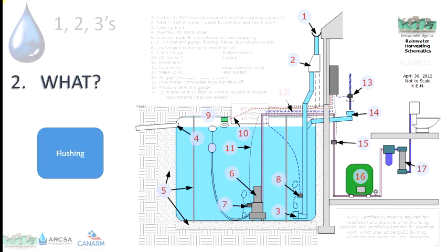And there's a floating intake which allows the water from about 6 inches below the surface, wherever that surface is, to be pulled into the pump. That is the sweet spot for good water in the tank. Not the very top, there's floaters always, and always going to be some sediment. And at the bottom there's going to be some sediment too, so we want to keep that off the bottom of the tank and not take the water off the top. And there's an overflow, number 4, so that the tank will always have an overflow.